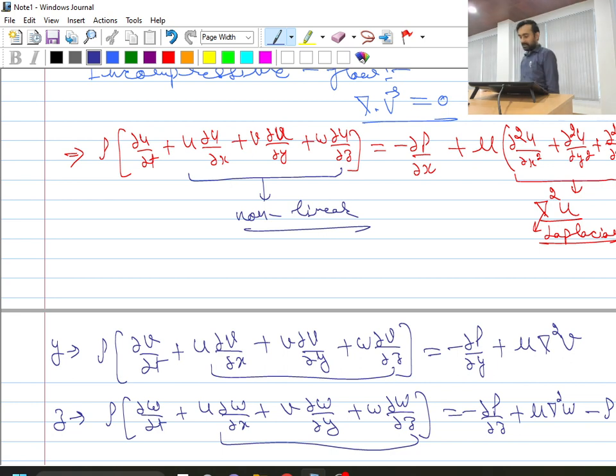And if you see, the highest order involved in the equation is second order. So we have non-linear terms, we have second order terms. So finding the complete analytical solution for a complex flow situation is not actually feasible. That's why the solution of this type of equations is applicable for very simplified situations. Analytical solution I'm talking about.